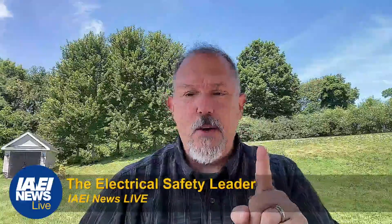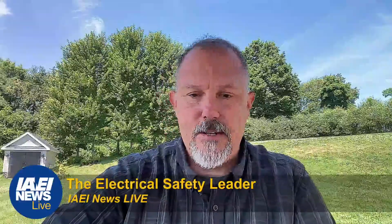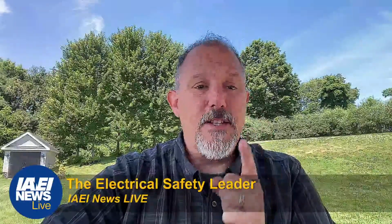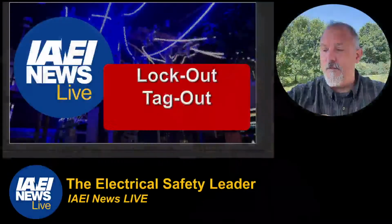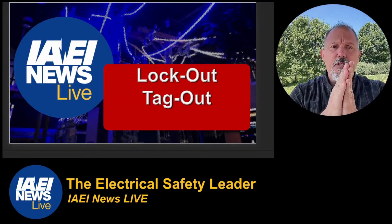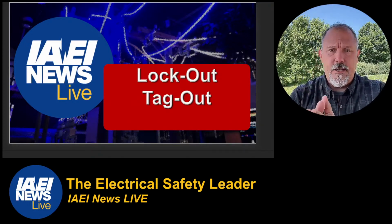Okay, everybody. So let's talk lockout, tagout. And I'm going to get off that web page and let's talk. I just want to make sure I get all this ready. Because lockout tagout is an important part of electrical safety. So when you think about lockout tagout, you should be thinking about establishing an electrically safe work condition.